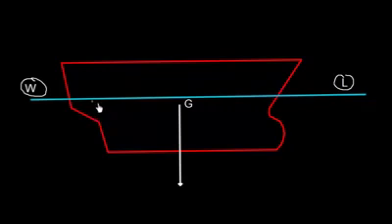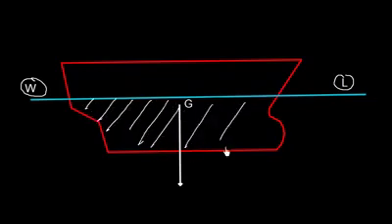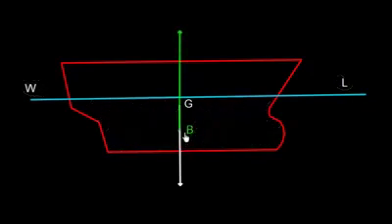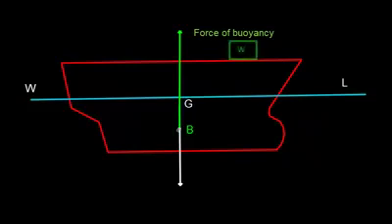So this means that this is my underwater area or underwater volume. This is my underwater portion. The center of buoyancy is the geometrical center of this underwater portion. The force of buoyancy acts vertically upward from a center of buoyancy. Well, it is acting like this.